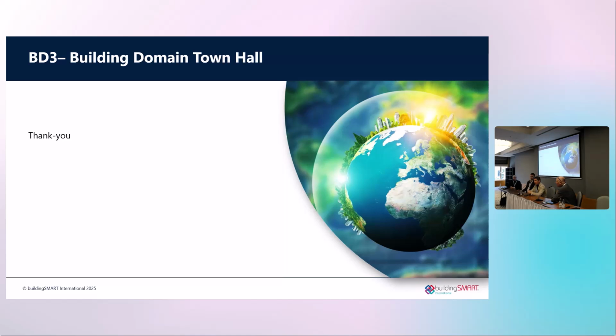That's an example, and the recommendation from our side, lessons learned, is better to use IFC space. But that was a different story because we have a real room. If you don't have a room, like an outside area, transportation area or overhead lines, you will not be able to create a room between, let's say, two high voltage pylons and say this is my secure area. That will be difficult, and that's what IFC spatial zone does.